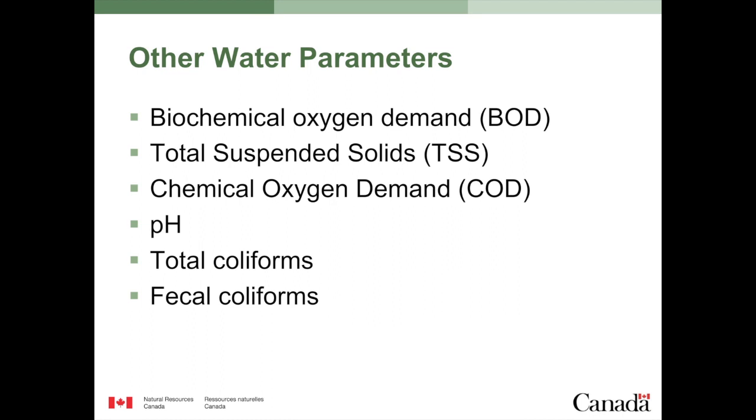It's starting to get on the high side, and it might start locking up some nutrients in the soils, but it also depends on your soil characteristics. Usually it was the EC and the SAR that were really the first indicators. After we got those through, then we would check for the others. Any of the labs that are now testing your water before you discharge have the capability of doing these other tests for you.